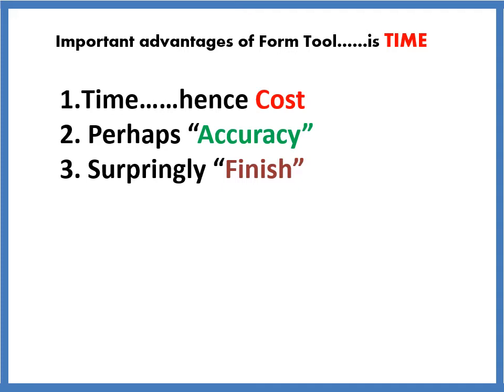When the same turned profile is machined with a form tool against a series of single point tools, the simple in-out stroke of the form tool allows the profile to be machined in about one third of the time. Given a large enough volume, this time saving can become attractive enough to justify the investment in a customized tool.